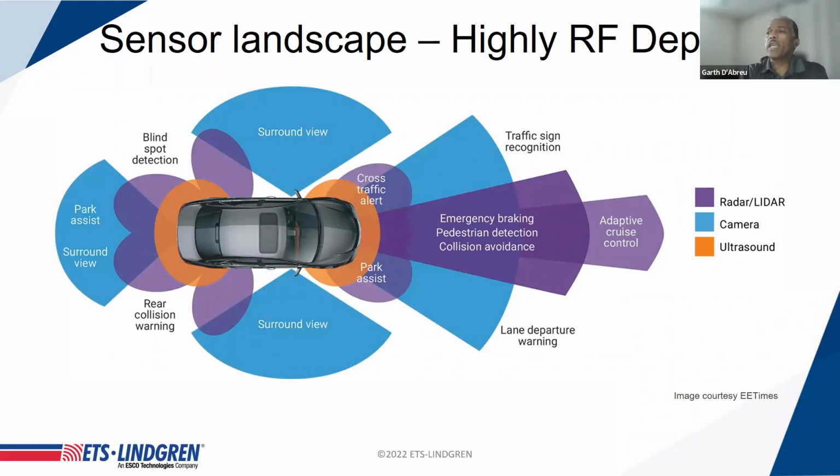At the same time, we have to be able to do the traditional type of component level and full vehicle level measurements. So as an example, we looked at the traditional immunity test of a full vehicle with the antenna directed at the reference position of the vehicle. And you're driving and making sure that the wipers work, the lights work, the horn works, and making sure that the brakes work and nothing is interfered with by this incident RF energy.